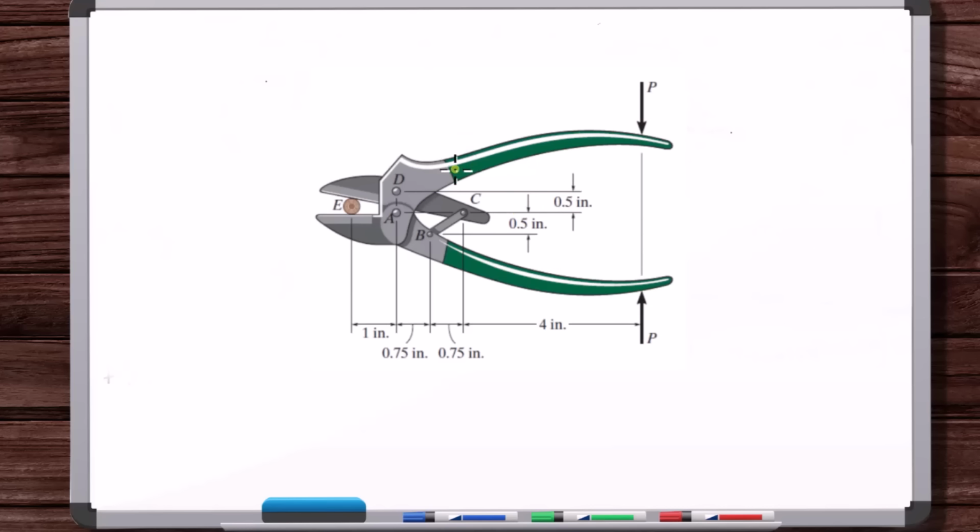But what else? Okay, we've got these pins here, but these are all rigid connections. But there's no exposed surface. There's nothing exposed here, or maybe here, right? Well, with the twig there's nothing exposed. The shear blades are contacting the twig, but that's not exposed. So this is it. This is the free body diagram for this.